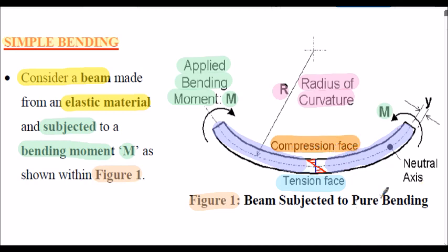As we've seen in previous presentations related to simple bending, the stress distribution across the beam, shown here, is of a triangular distribution. We have zero stress at what's termed the neutral axis of the beam, centre of the beam in this case, and then the stress varies linearly from the neutral axis to the maximum stress.